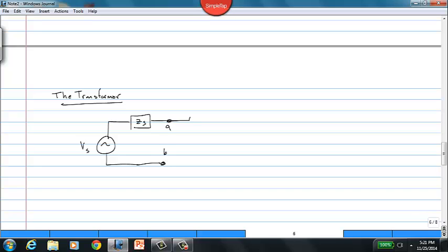So now we're drawing the transformer. We've got a resistor and an inductor. The transformer is modeled by a series resistance R1 and a series inductance L1. I'm going to give this a dot up the top. The secondary side of the transformer also has an inductor. It is then connected to a series resistance R2. This is L2. I'm going to give it a dot here.